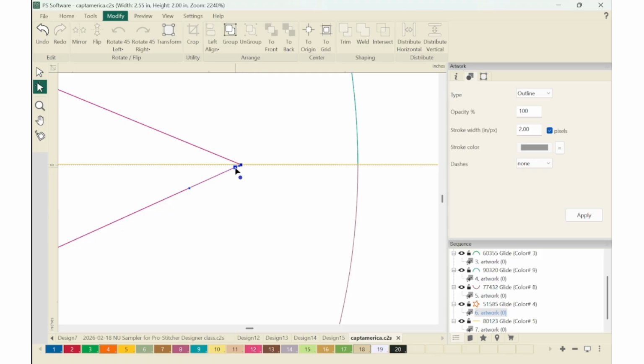And when I do that, it made the start and end points right here where I had come off to the side. So I'm going to click on that endpoint, right click and delete that one. So now I've got my start point and my end point. And again, it's okay if they're split right now. At the end, when I get everything put together, it's going to look just fine. But I need to have them split so that I don't close any shapes. When you're connecting a line, you cannot have a closed shape.